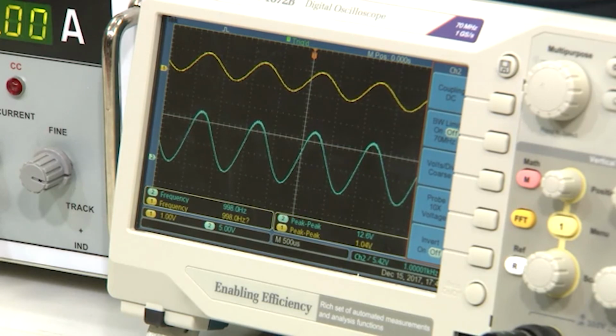The non-inverting amplifier formula is V out equals 1 plus Rf by R1 into V in. The inverting amplifier formula is V out equals minus Rf by Rin into V in. So using that formula, if you calculate the theoretical amplification or gain and the actual gain, you will see a little bit of difference, not significant.